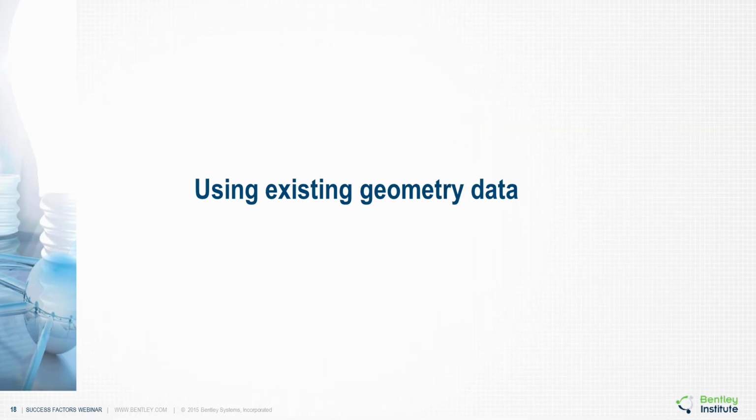In this section we will look at how you can make use of existing geometry. In particular, we will look at how MAXSURF markers can be generated. Markers can then be used to create both tri-mesh and NURBS surface models in MAXSURF, so the workflow and tools shown are often useful irrespective of the type of model desired.